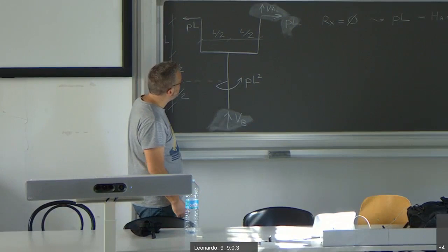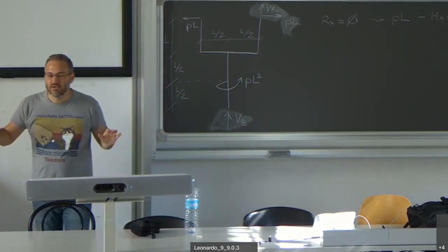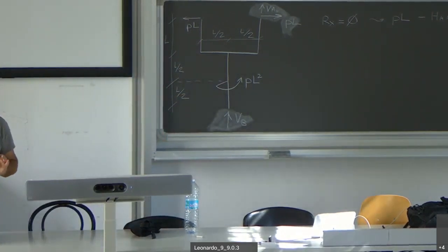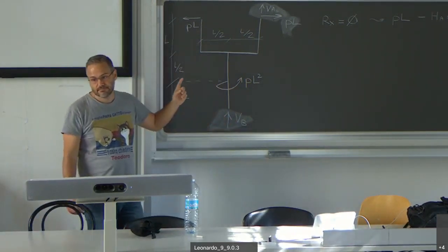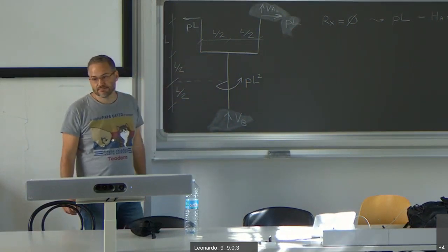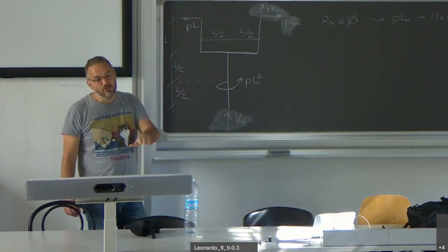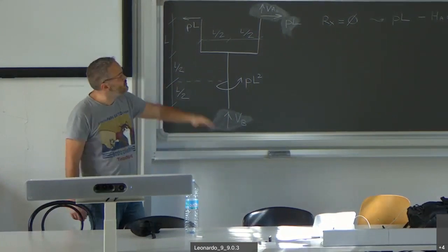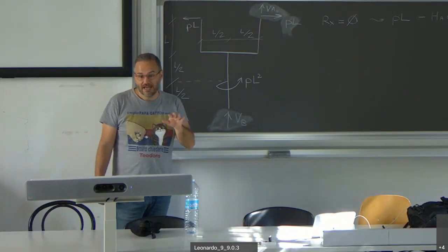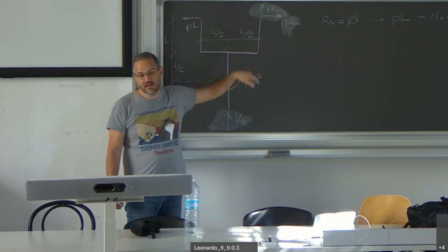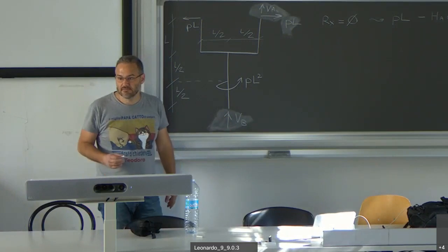Then I have to work out VA and VB without any calculation. There are no vertical forces on the structure other than VA and VB. They both point upwards. If they are both different from 0, the structure would move in the vertical direction. So before doing any calculation, I know that if one is positive, the other will be negative, in order for them to counteract each other, okay?